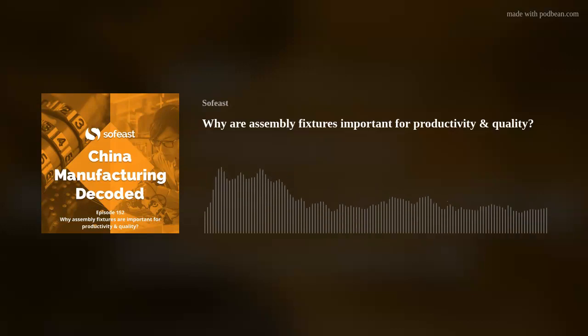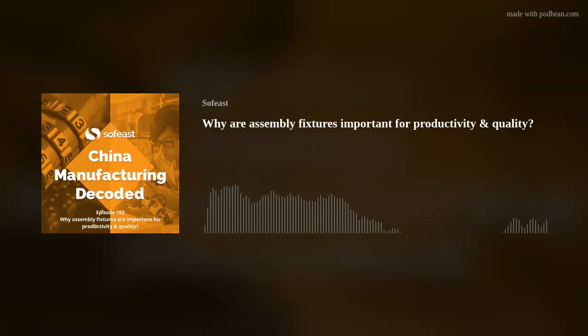Interesting. Right, because there's a lot of products that are supposed to contain water, but you don't want to test with water because then how do you make sure it dries and all that kind of thing? It's very common. Yes, that's right. You need to fill up the water, and once it's watertight, you need to empty it. You're going to dry it before you assemble it. It's very complex. So air is a very good process of checking whether a system is watertight or airtight in this case. So that's good.